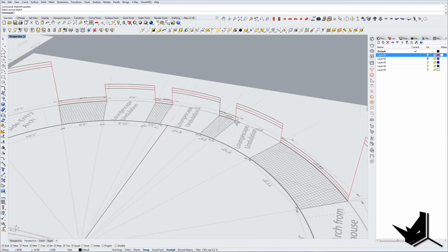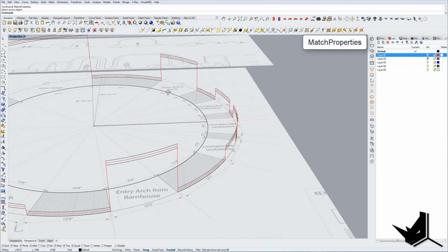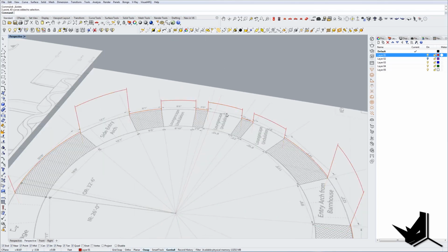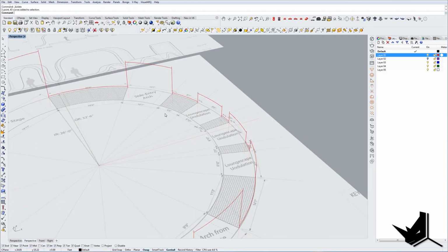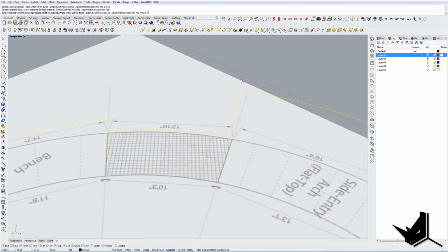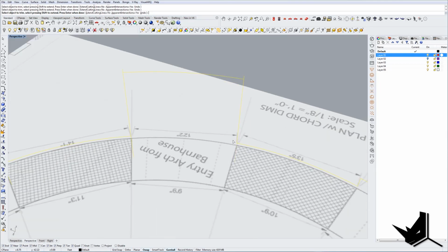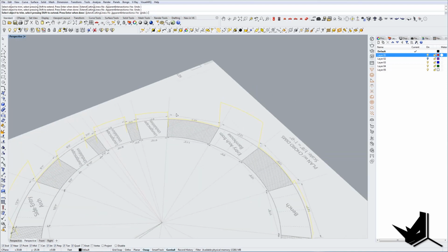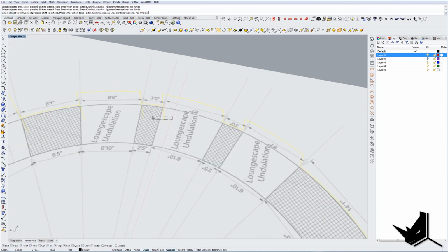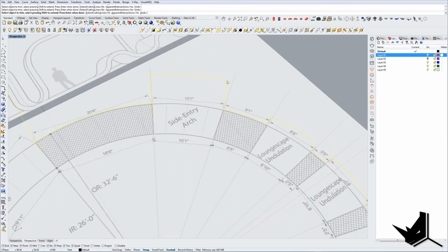All right. So now I'm going to select all of these red ones. I missed one here. I'm going to say select by color, and I'm going to isolate them. Now I need to trim them out. So I'm going to select the trim option and trim everything, both tops and bottoms. You'll see why this is important in a minute. We want to create nice fillets in these elements, so that's why we need the middle of that structure. So let's move on.